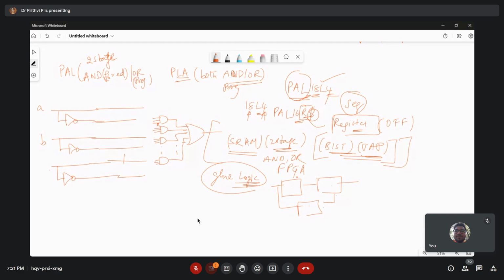The more inputs you have, the denser the PLDs will be. Otherwise, we have the limitation of two-level logic only. If more inputs have to be implemented, other aspects we have to see are how much circuit complexity there is and how much wiring there is. All these things will decide the size or the type of FPGA you have to use.